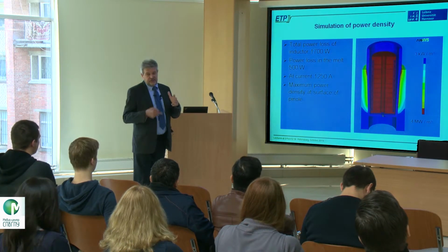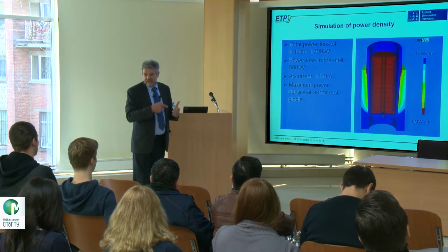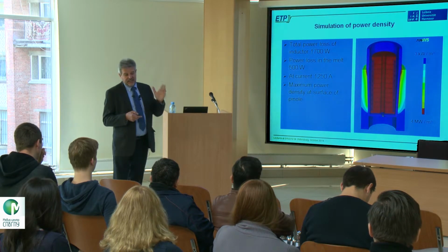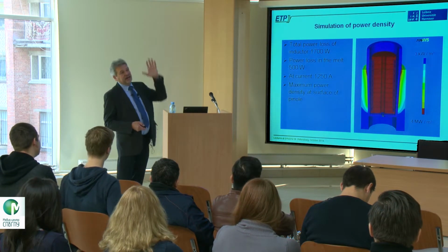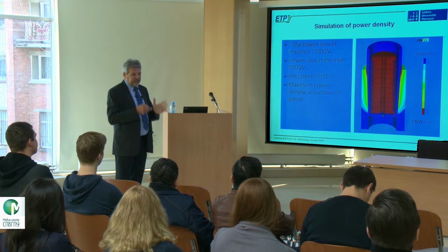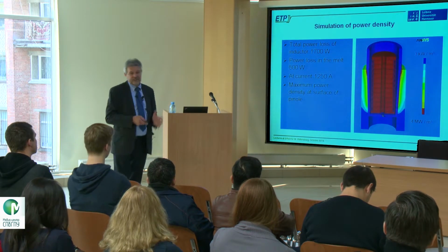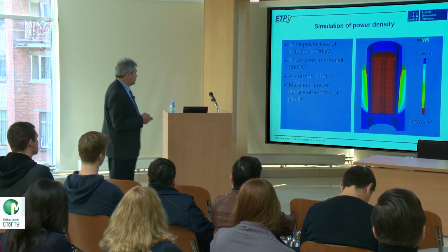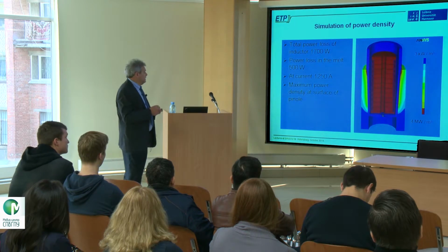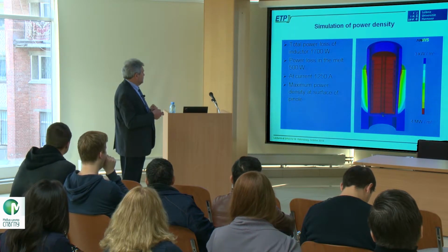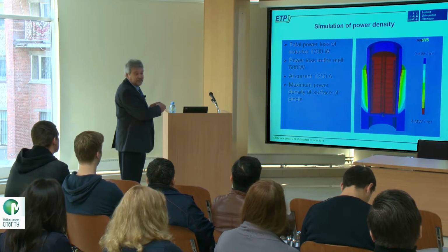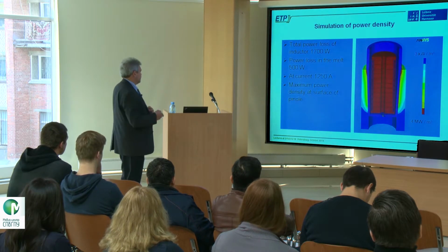But there's a clear dependence on frequency. Always in such applications, for low frequency, the Lorentz forces are high and the Joule heat is low. For high frequency, Lorentz forces are very small and the heat is high. So for really heating, you need high frequency. For steering, you always need low frequencies. This is a general rule. Therefore 50 hertz was used, because it was also the simplest way. The losses here were 500 watt only, which is quite low for induction heating, typically.